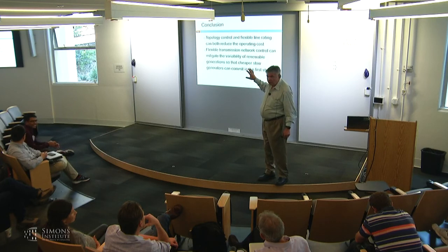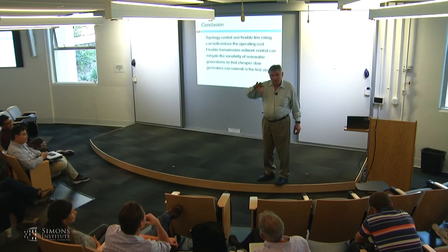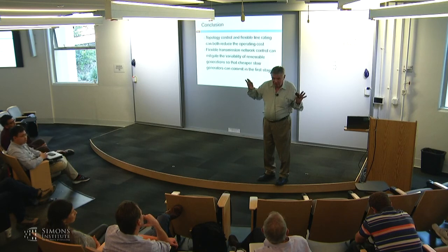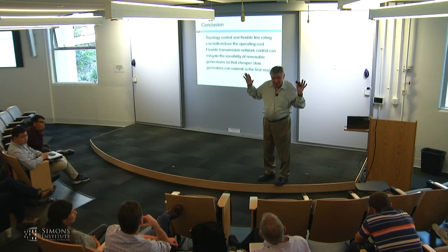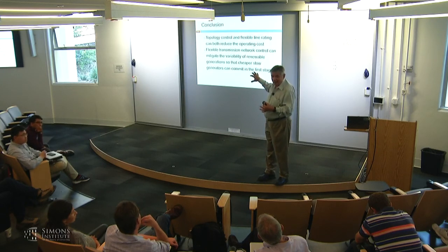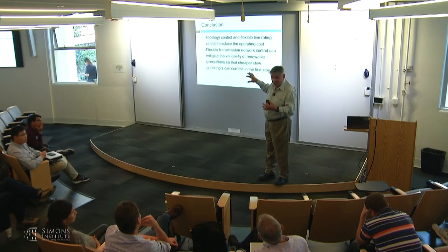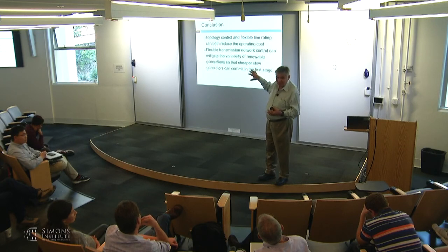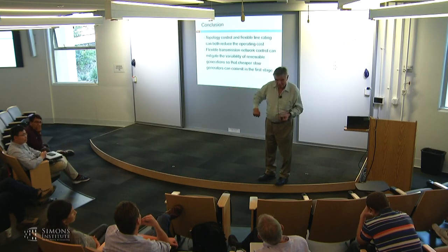But that's why here we're focusing on using line switching as recourse. Once you have contingencies, the ISO basically has full authority. You can run the lines at emergency ratings for 30 minutes, you can switch lines, you can take whatever action it takes to mitigate contingencies. So we are trying to recognize that here and say, if you anticipate that you'll be able to mitigate contingencies with those actions, how can you save money in the day-ahead stage? And that's what we are doing.